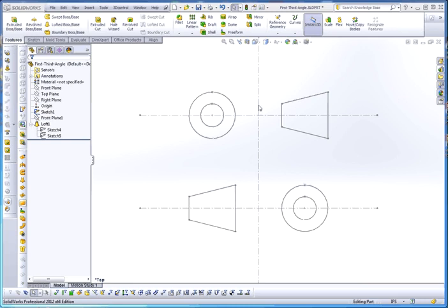So what you're looking at is a symbol up here. I drew this in a sketch format in Solidworks. What you're looking at on the top is a third angle projection, and what you're looking at on the bottom is a first angle projection. Remember the third angle projection. That's a test question, by the way. That's what we use primarily in the United States. That's the one on the top.